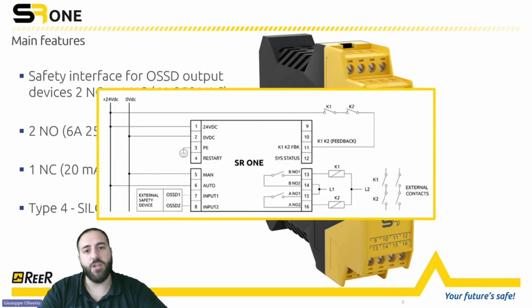So as you can see here, we have the manual or automatic selection. Based on how you wire those two inputs, you will decide the behavior of the contact. So if you want to do the automatic reset like this example, or the manual reset, the reset button would be connected to pin number 4.